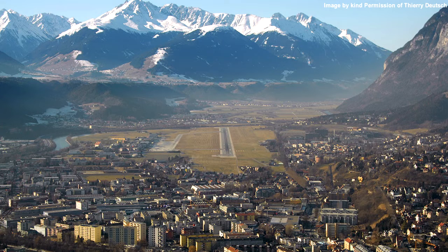For these reasons, certain areas of local airspace must be regarded as integral parts of the aerodrome environment. Thus, an instrument approach runway will have an established obstacle-free surface as a basis upon which the instrument procedure is designed and the minima established. For a precision approach runway, the maintenance of the obstacle-free surface is particularly critical to protect the minimum descent altitude established for the safety of aircraft movements.